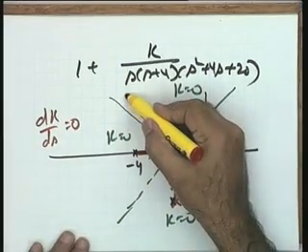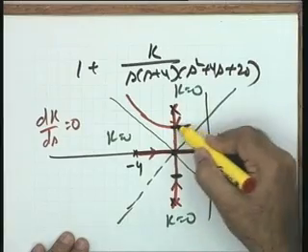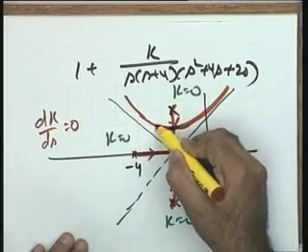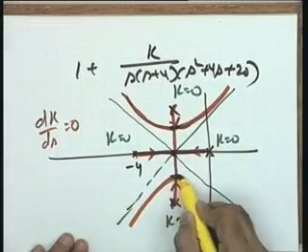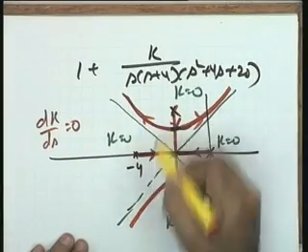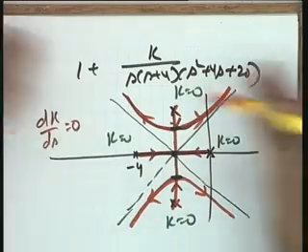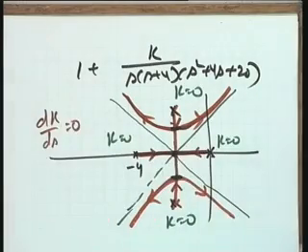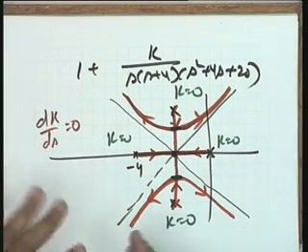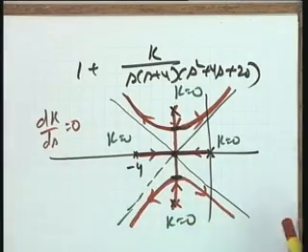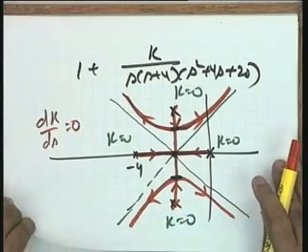And therefore, in this particular case, you have to apply your intuitive eye on this. This is the complete root locus plot. More rules are required to get this particular plot. This is the complete root locus plot. You see there are no zeros, so all the 4 branches are terminating at infinity along the asymptotes. All the 4 branches are terminating, and that way you are getting a root locus plot where there are 3 breakaway points.